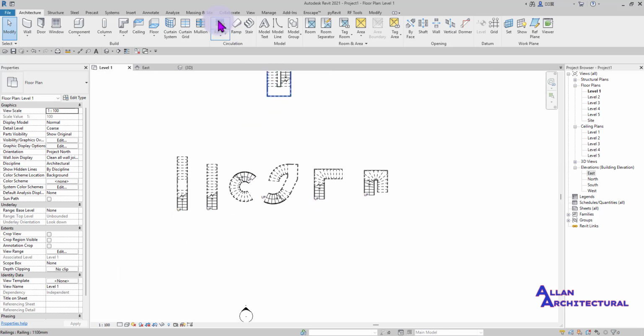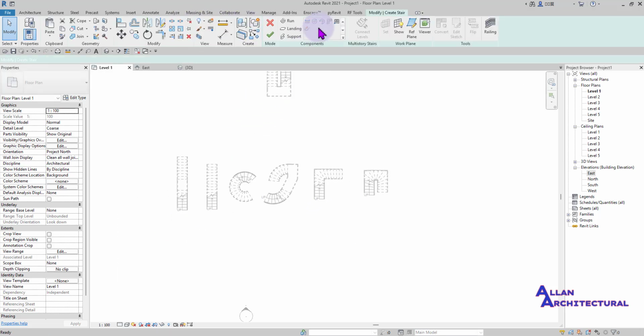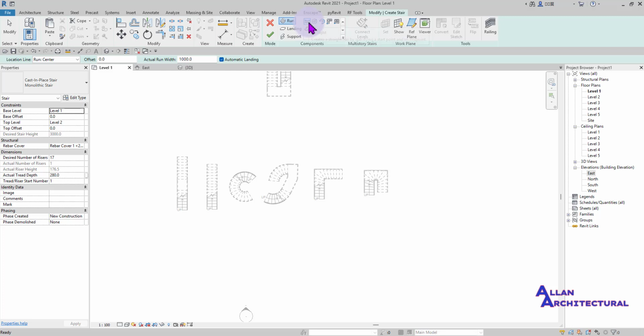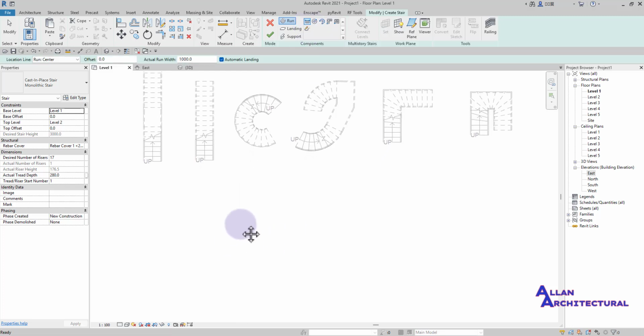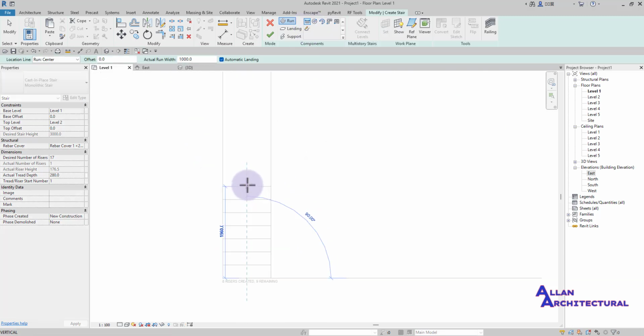It's very simple. When you get back into your stair icon, you just have to make sure you click on this straight run staircase, and then I like to make sure I keep all those risers on an even number. So if I have 8 risers created, I want to make sure I also have an even number, another 8 risers remaining for the other staircase.